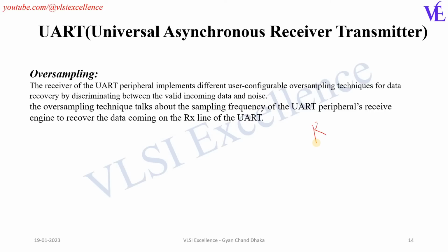UART receiver. The UART receiver can oversample the data at a higher frequency, or at a higher baud rate. If the UART receiver wants to sample the data at a higher baud rate, it has to generate a baud frequency which is a multiple of the transmitter baud rate. Suppose the oversampling is 16 times. The receiver is now sampling the data at a baud rate of 16R.